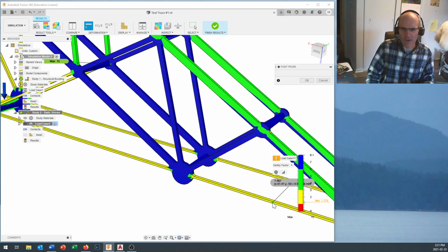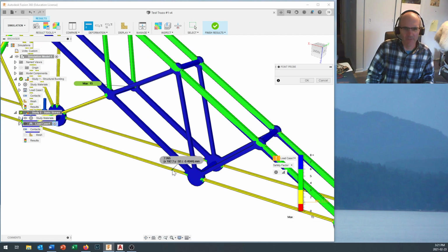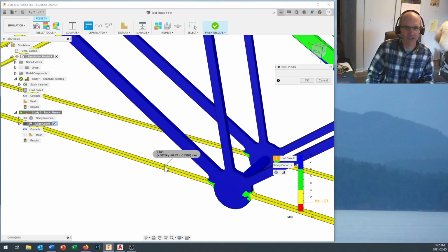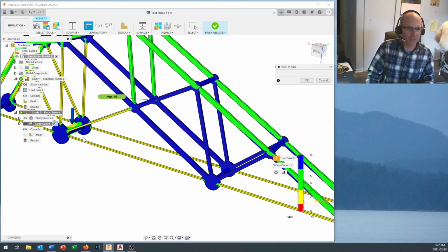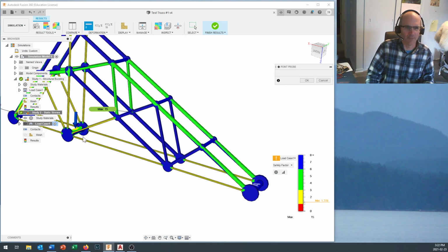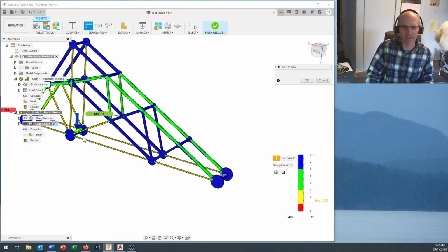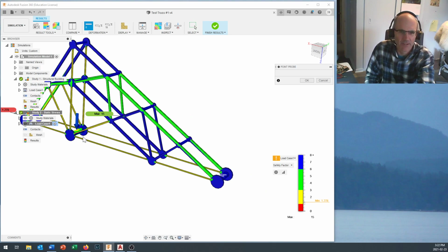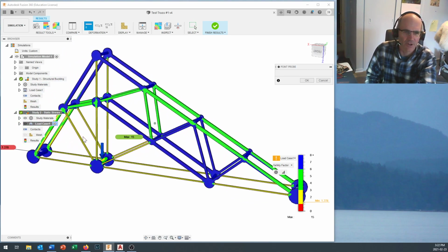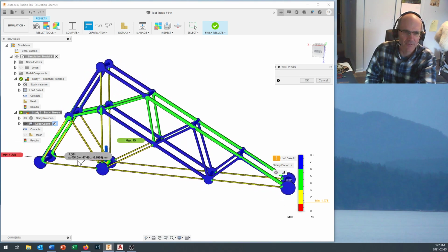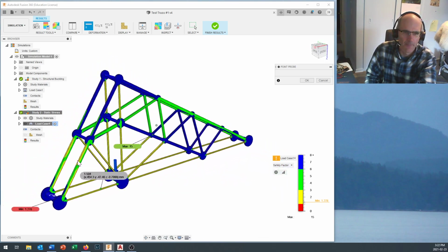But down along the bottom right here, this member is all like 1.5. We get up to 2 in there kind of. You know, maybe I just needed to make that bottom just that hair thicker so that it's a little bit safer. It doesn't add that much to the mass, but it would definitely ensure that I'm less likely to have a structural failure due to a tensile failure in the bottom right here.